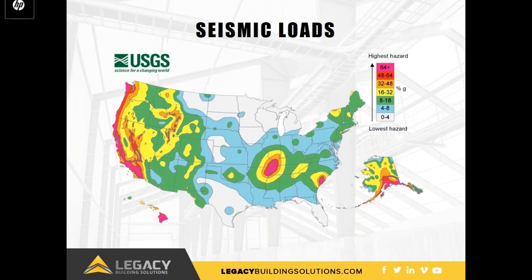Seismic ratings are defined by the occupancy rating of the building as well as the expected level of building movement during seismic events. Tension fabric buildings are a great option for areas and applications with seismic concerns. The flexible nature of the fabric allows for some movement of the frames without damaging the cladding.